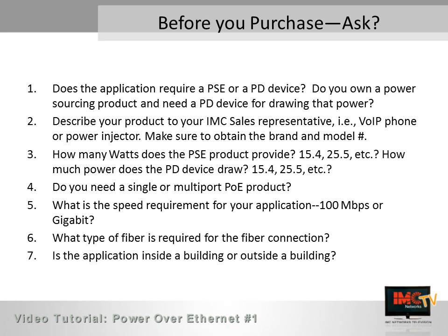The first would be, does the application require a PSE or a PD device? Do you own the power sourcing equipment and need a PD device for drawing that power, for example? The second question would be to obtain the information about the product that they do have or are considering, for example, a VoIP phone or a power injector. Make sure to obtain the brand and the model number because you're going to find yourself doing some more research.